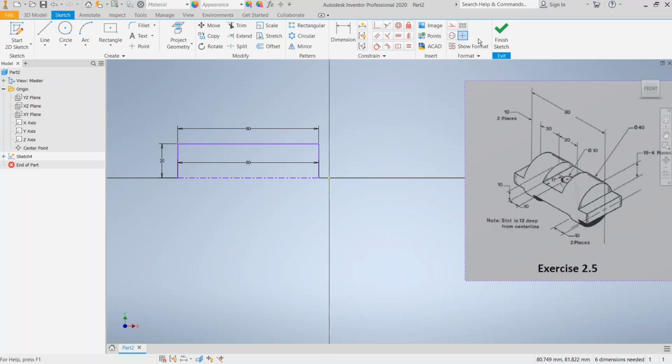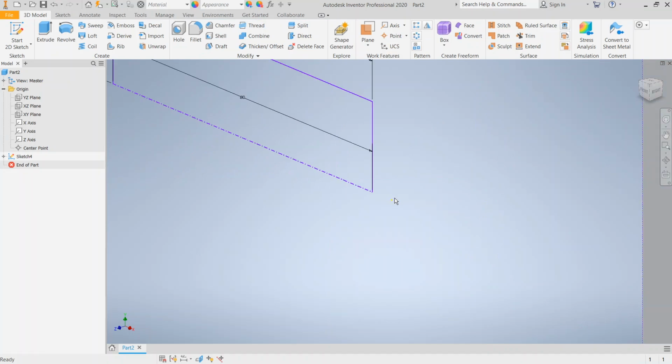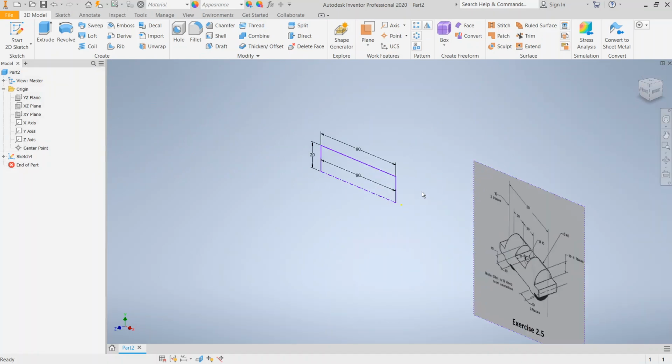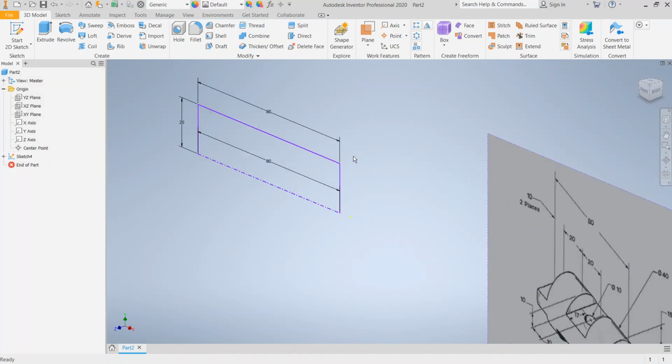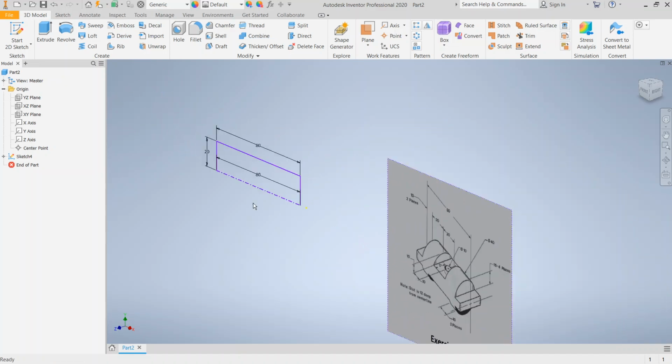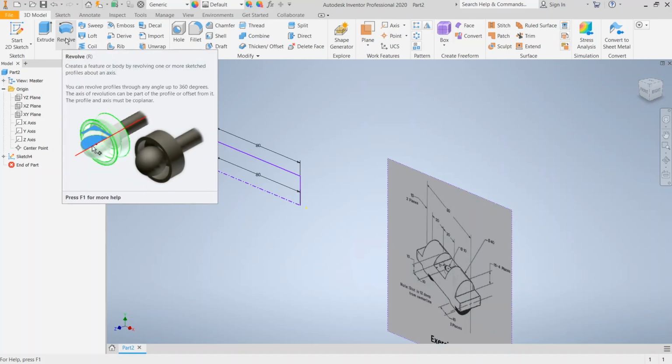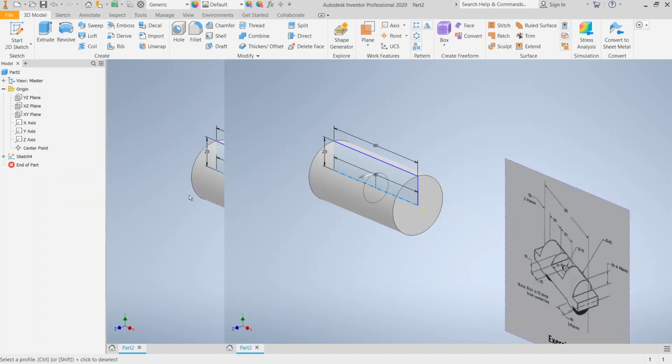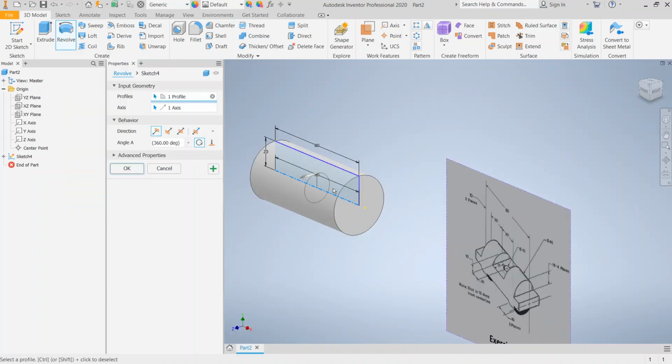So we'll just finish the sketch now, and then we go to the revolve function. So if I finish my sketch, as you can see, that is just a half. Don't worry about these cutouts, we'll do them later using the work planes. So to revolve, there's a revolve function. You can also read there. Click on revolve, and it just revolves automatically for us.